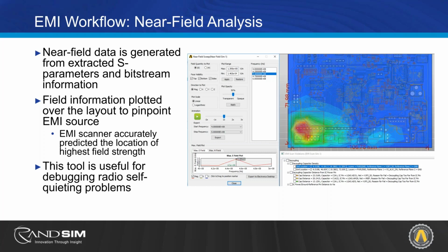Okay. Is there a preference for import ODB++ or IPC 2581? And is there any support for Gerber import? So all of those can be imported. The preferred import is most certainly ODB++. And the reason being is that it's all natively packaged together.